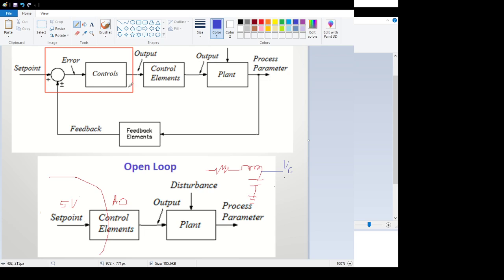And then what I'm going to do is I'm going to apply proportional control. So I'm going to have a gain factor here, call it KP, which is going to be proportional control. So I'm going to feed back the voltage across my capacitor into my PLC. It's going to generate an error signal, which is the difference between the set point and my voltage across my capacitor. Multiply that times the gain, and then feed that into the system, this RLC circuit that I have down here. So that's what we're going to control.